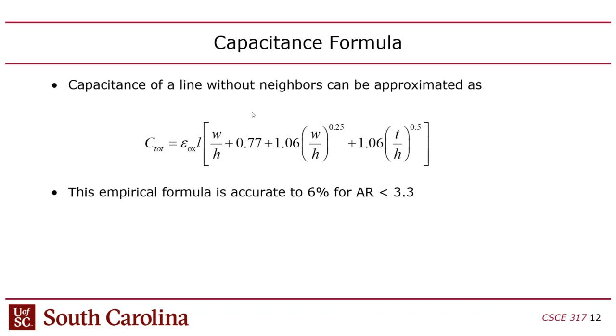They have different types. They have FR4, and then they have Rogers material. But anyway, the lower the number, the better. So you want the dielectric constant ideally to be lower. In the case of silicon dioxide, it's 3.7. And in the case of a circuit board, if you have FR4 material, it would be 4.